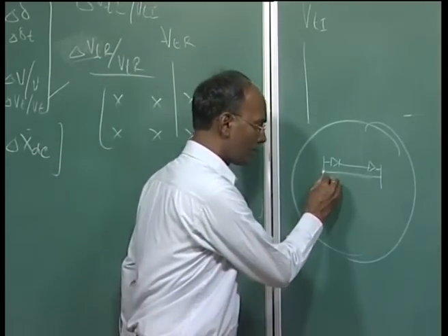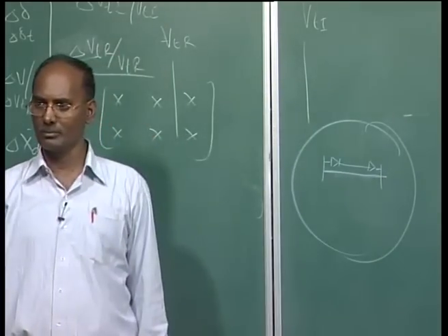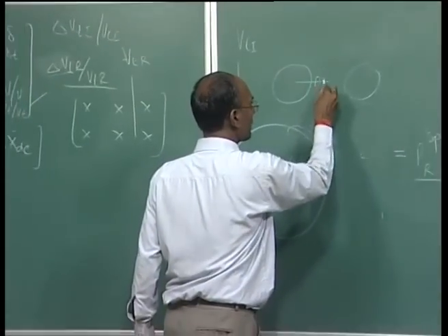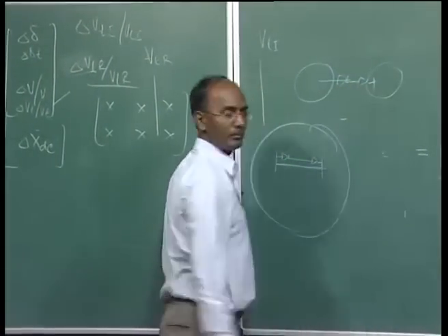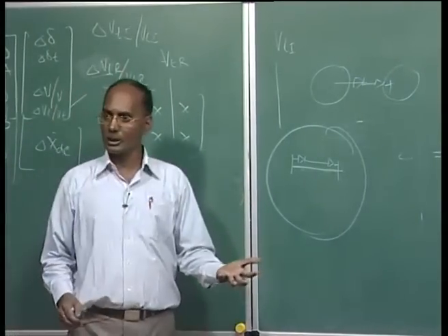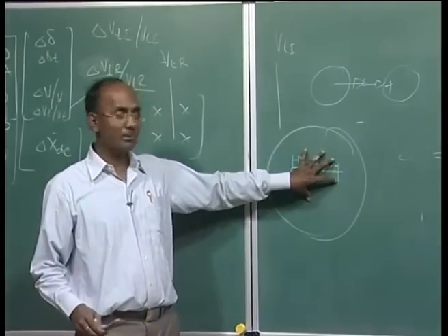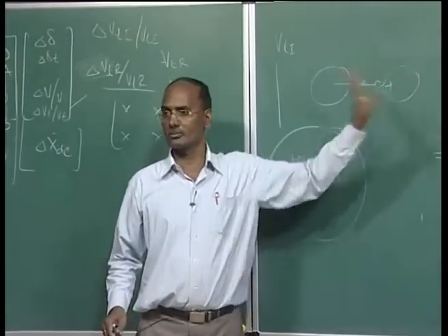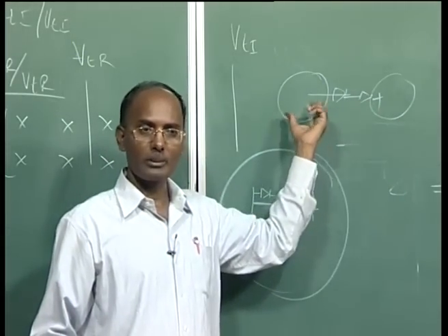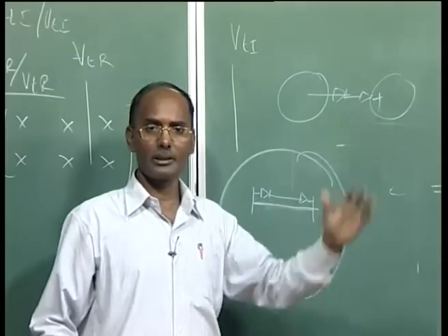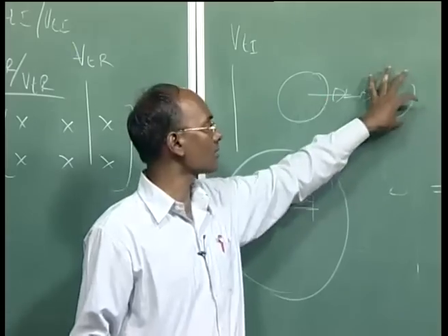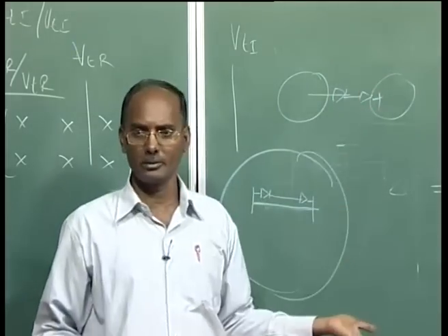Another possibility is that you can have a parallel direct AC line. Another option is that two independent systems are connected by the DC system and they are operating with different frequencies. So 3 scenarios can be there: inside the AC system, or two different frequency systems. If there are two different frequency systems, they must be solved separately because they operate at different frequencies. So here it is just the P and Q, and here also is the injection, and you can just solve it.